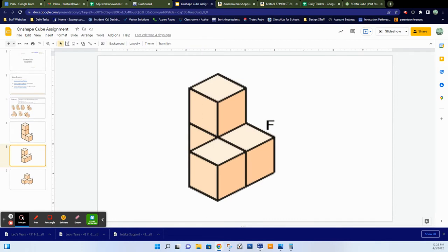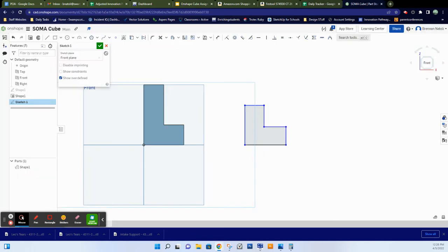So looking at our drawing, we're going to define these. So there's 2 blocks here by 2 blocks. So I'm going to click the dimension tool, D on the keyboard, or click up here. Now what I do is click in between the points or the specific line. So I click and drag. This will be 2, enter. The bottom line will be 2, enter as well. And then we know the width of the cubes is 1 inch. So I'm going to make sure these are each 1 inch. This is 1 inch.